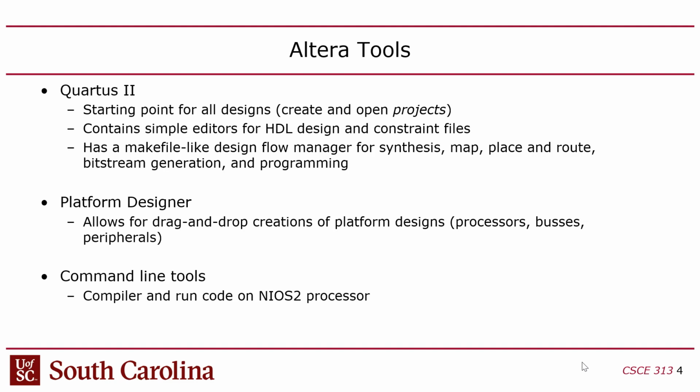The only other way to do multi-core where it's more transparent is if you have an operating system that's multi-core aware, that has a scheduler that can dispatch and load balance the processors dynamically. But in a bare metal system with no OS, you basically have to run separate programs on separate CPUs, and each program has to use a different memory address, because there's no memory management unit, there are no virtual addresses either, so it's all physical addressing, right?